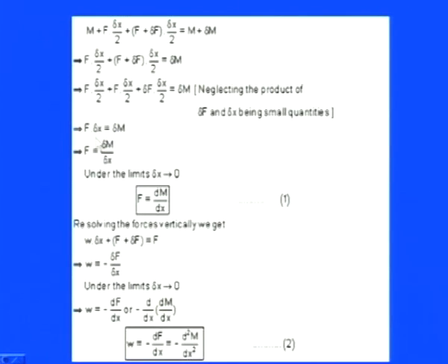So if I conclude that part for a small section where the shearing force as well as the bending moment is applied, we have the final conclusion as far as shear force and bending moment are concerned. F equals dM by dx, or if I apply dx tends to 0, the shear force equals the rate of change of bending moment in the x domain. That means wherever the change of moment is there, it will apply the shear force on the section.